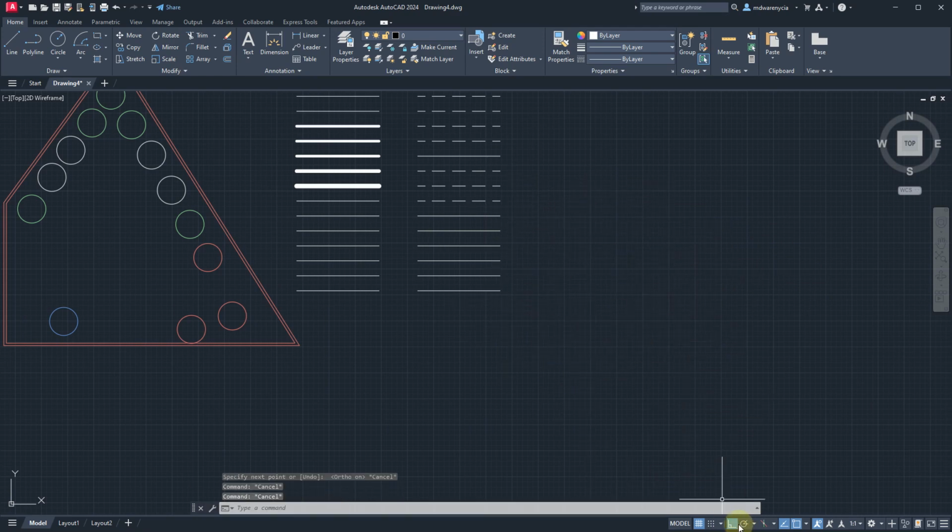And I don't think it's got any settings. It's just sort of on or off. And you can't have both of these on at the same time. So if you have polar on, that's what you're going to want. Again, you have the settings here. We can go in and do crazy small adjustments. So if I want 5 degrees, it's going to snap every 5 degrees here. Or you could just turn it off and be a rebel and never have any tool assist, which is crazy.